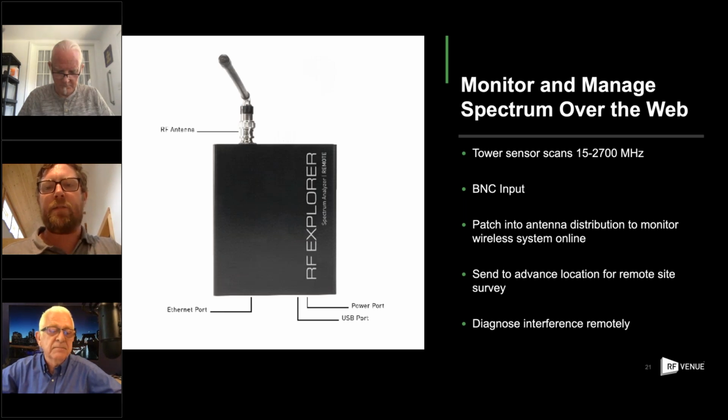Yeah, and that's why when you're using the handheld unit, that'll vary automatically in the device to try to give you as quick a span with the best possible results. But on the software side, when you have it interfaced on the computer, we can override that and say, no, we need 25 kilohertz steps no matter what.